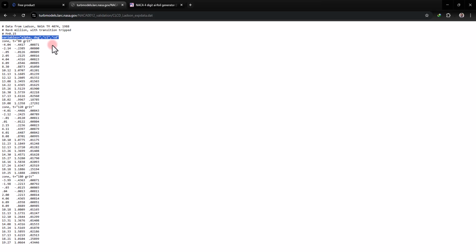What we're gonna investigate is the airfoil performance exactly at zero angle of attack. So within this column, we guess this is the closest one to zero angle of attack, and we're gonna use that. The other important thing about this is the Reynolds number. It shows the Reynolds number equals 6 million, and we have to keep that in our calculations from now on.